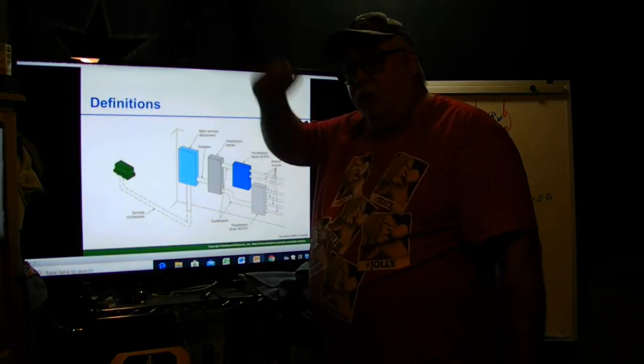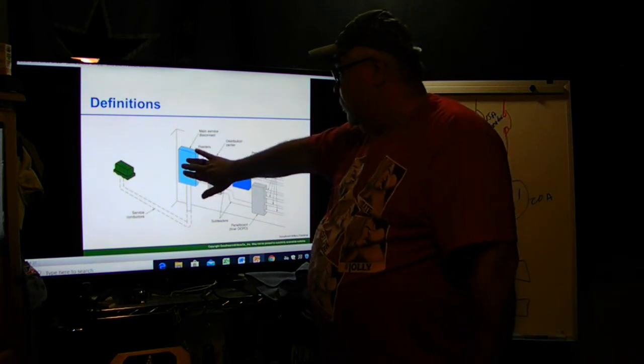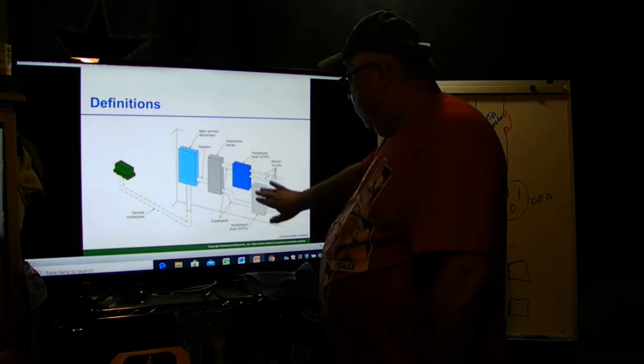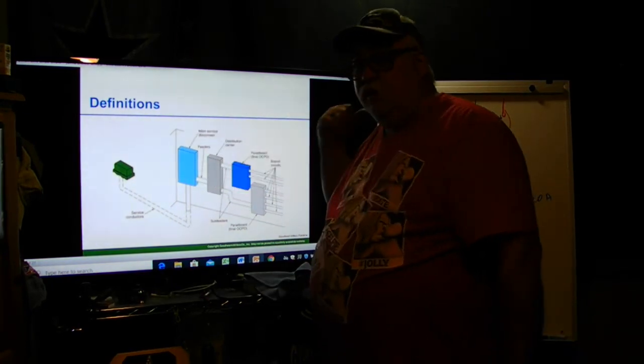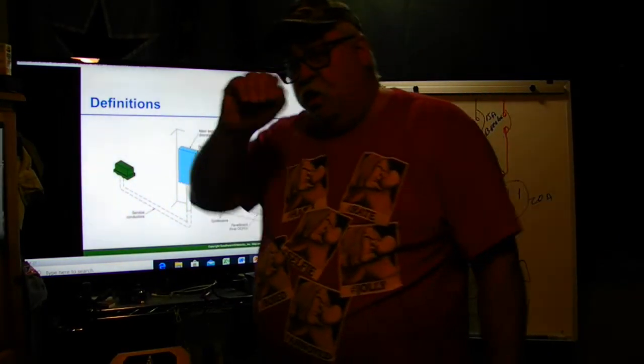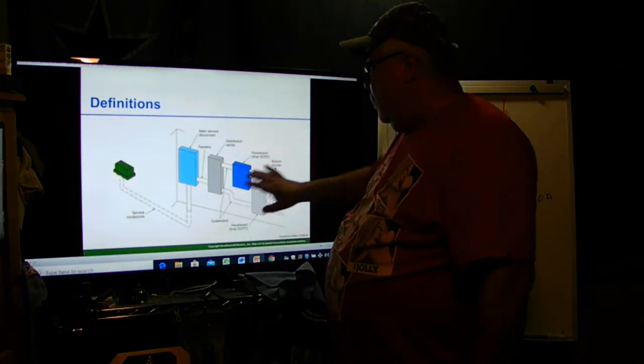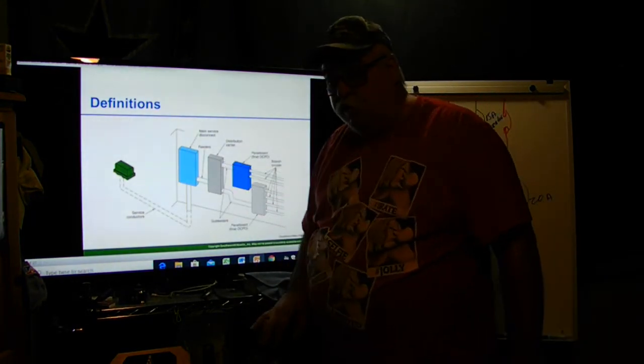So from here is just the main disconnect. So you got to turn power off the whole building. This is where you go. You don't have to worry about going here and going here and going there. This may be outside. This may be inside a main distribution, and all your panels that are within that building would come out of your distribution center.